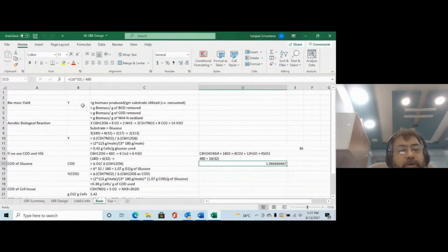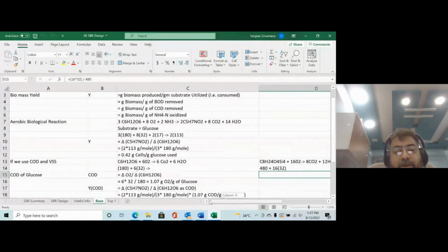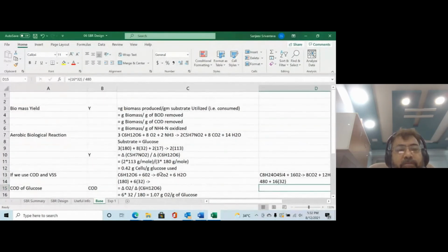Before you start trying to use tools, sewage treatment plant information and what the business is, that is one thing that I've done in 2 days. Then we come to designs. A designer must understand a few basic terms. One term is called yield. Yield means the yield of biomass. Yesterday when I was talking about how COD becomes cell, COD becoming cell means yield. There are some formulas given here. You have to read them yourself to understand the aerobic biological reaction.